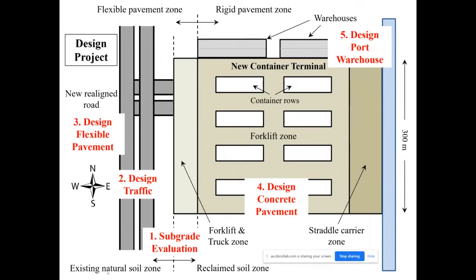For mechanistic design, we will learn how to convert that CBR to the Young modulus, to the elastic properties of the soil. And also for numerical analysis, we need to have access to those elastic properties. So in the first phase of this project, we are working on subgrade evaluation.